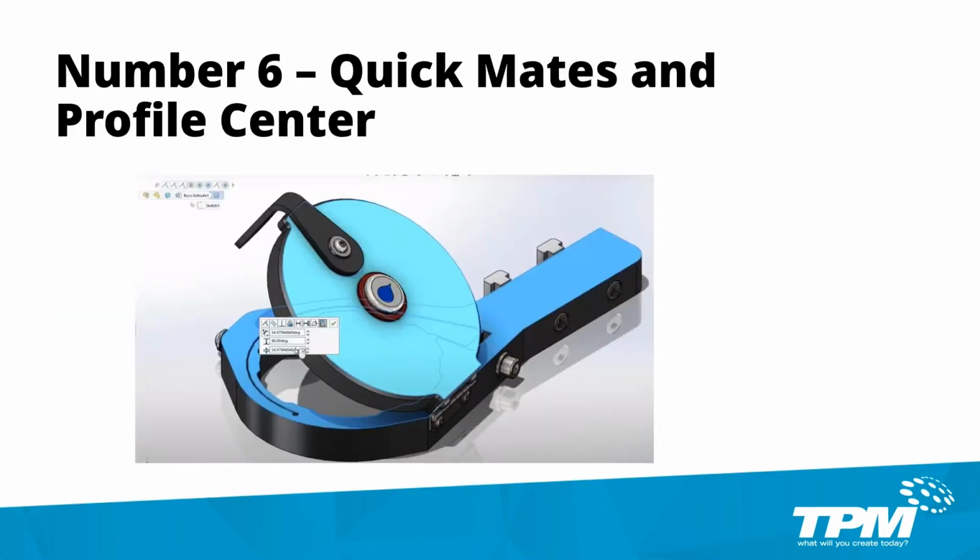This next one, number 6, I think this is probably one of the more powerful ones for me, the Quick Mates toolbar. And this one was introduced in 2014, but quite honestly, I think the introduction of all of the mates on the Quick Mates toolbar has really saved me a lot of time. That coupled with the D key, because when you click on a model, you click the D key, you get breadcrumbs from the top of your screen here to your mouse, and it allows you to sort through and pick on planes and axes and things that are referencing those geometries.